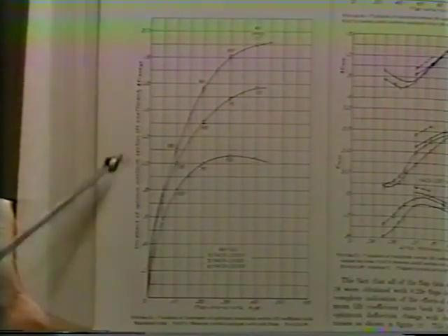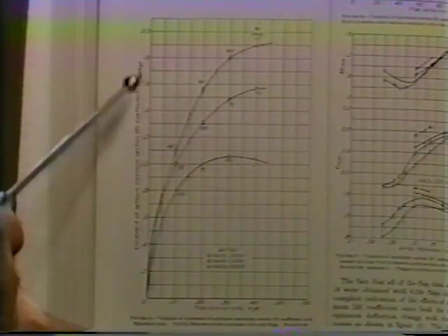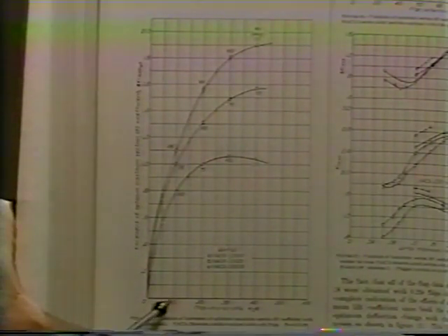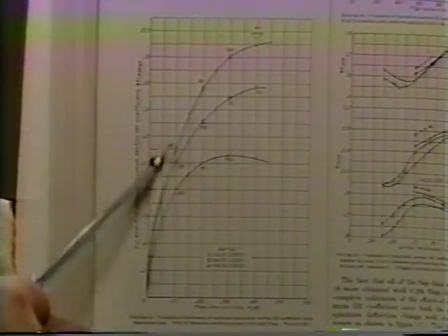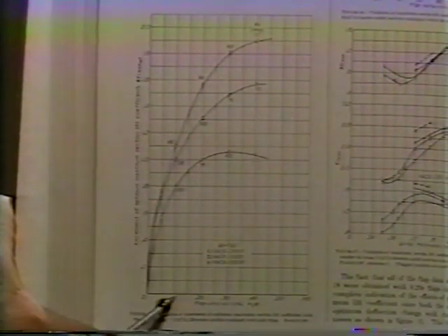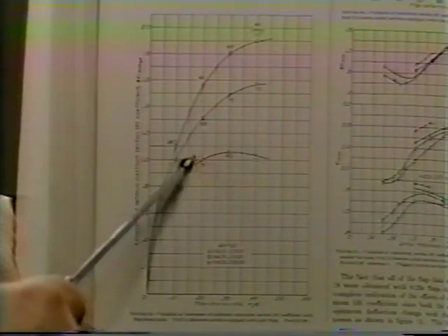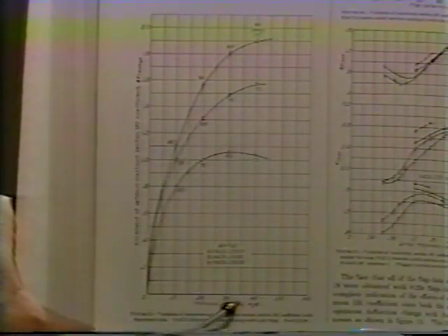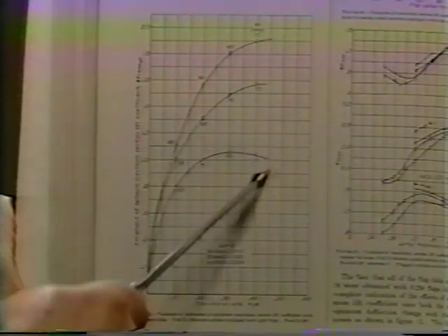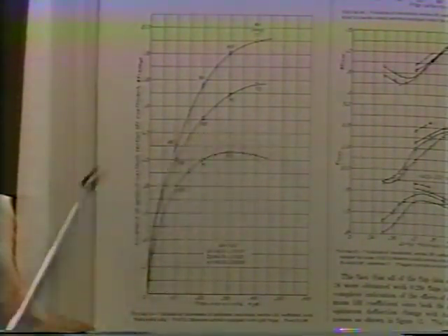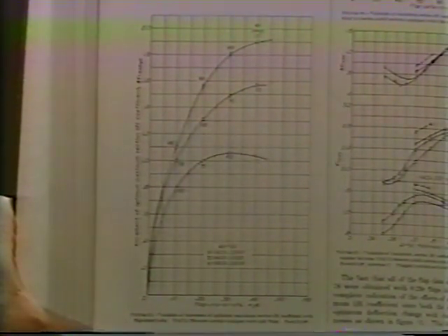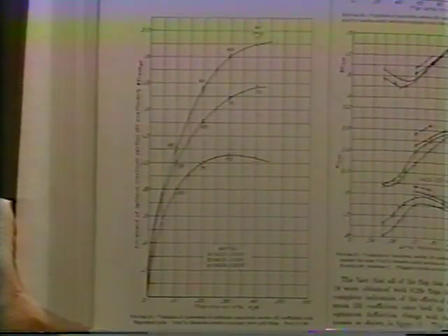That part's not important, nor even the airfoil section, but the thing to notice here is this. Here is the increase in lift coefficient, the delta CL. This is only 10% of chord of the flap compared to the whole wing, and yet you get a sizable increase. When you go from 10 to 20%, you get an increase, but not that much. You can even go 30 or 40% chord, and on a 12% thick airfoil, you've hardly gotten any benefit of the increased chord of the wing.